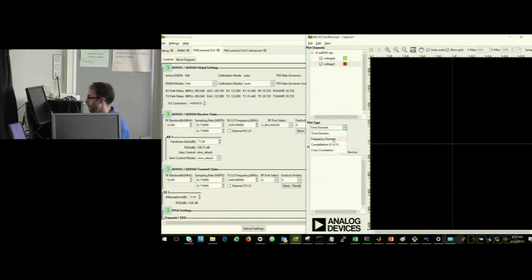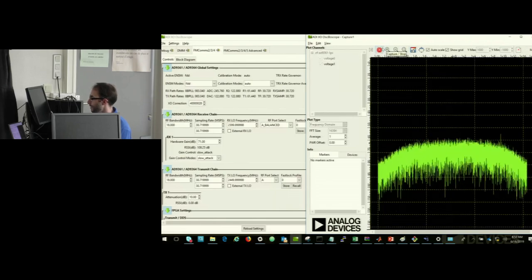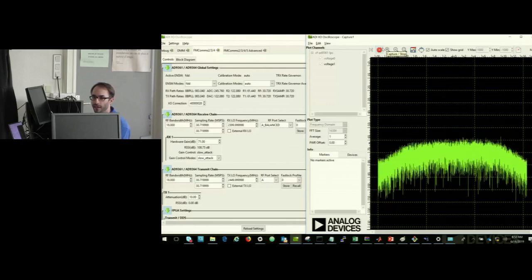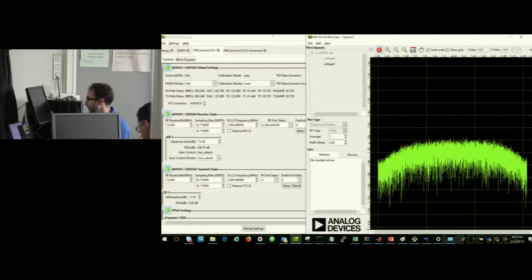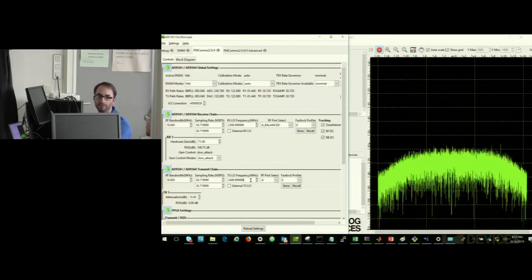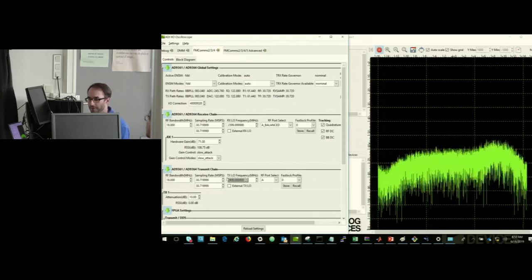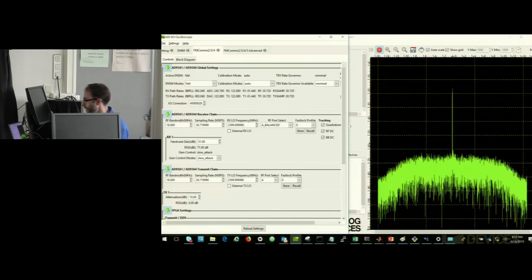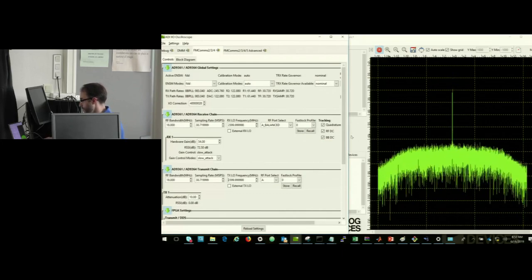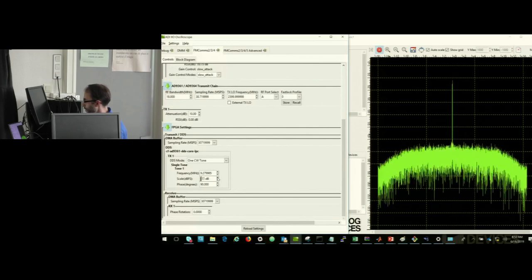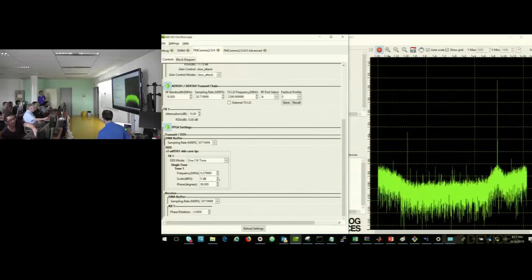Okay. Now, I'm going to go back to the capture window here and select voltage 0 and voltage 1. Actually, I'm going to change this to a frequency domain plot first, and then select voltage 0, voltage 1. This is just I and Q of the first channel. I'll hit play, and I'm just pulling back data. This is really useful for simple visualization, bringing it into the lab, making sure the part's working. And then I'll match the LOs together so I can see what I'm transmitting. And you can see the LO from the transmitter.